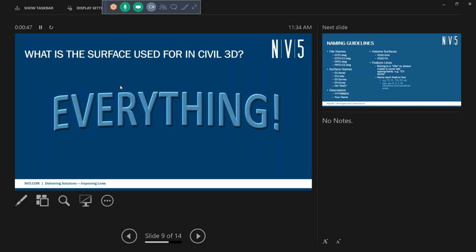Anytime we want to join or match existing planimetrics, like curb and gutter, retaining walls, settings where we set elevations to the 100th, the required level of accuracy is very high. So what type of data would we want to use on that application? Survey data. What type of survey data? Total station, right? That would obviously be the best. Sometimes we're only going to have GPS. Then what do you do?